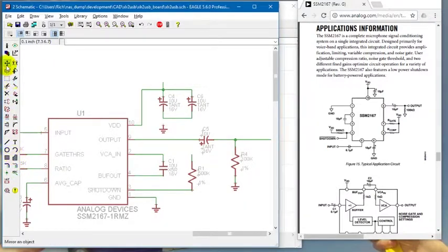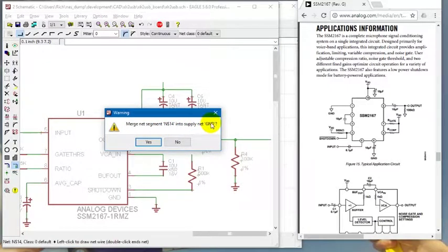Watch what happens when I connect ground here, which has never been connected to anybody before. By the way, ground has been getting names. All these other guys right here, ground, ground, ground. When we created those special supply pins in the library editor, we called them the supply type. So as I connect things to it, the name ground is an explicit name. Anybody connected to that symbol must be called ground.